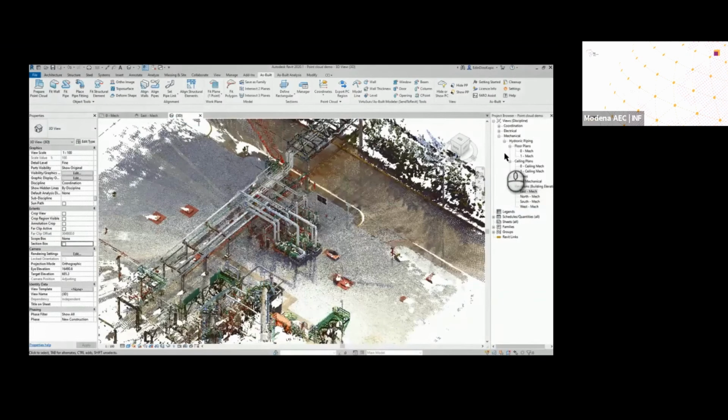Modeling pipes within your Revit package is sometimes a frustrating part, especially when it comes to utilizing pipes within a point cloud. The idea here is with the AsBuilt package, we can get AsBuilt to draw in the pipes for us. So within this demonstration, I'd like to show you how I utilize the fit pipe, place fitting, and of course align pipes element.